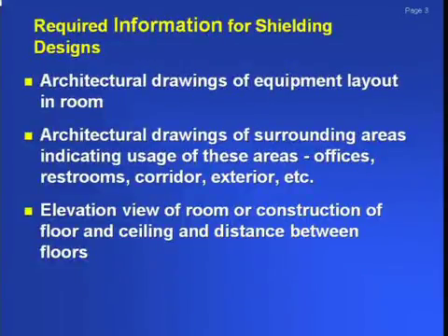What will you need to do a shielding design? Well, obviously you need the architectural drawings, at least the initial ones, of the equipment layout in the room. The first time you do one, you will make modifications 99% of the time. You will get some type of generic drawing, and then you will adjust the thickness of your barriers. Rarely have I had an architect that can give me a plan with no physics input and have it correct the first time.